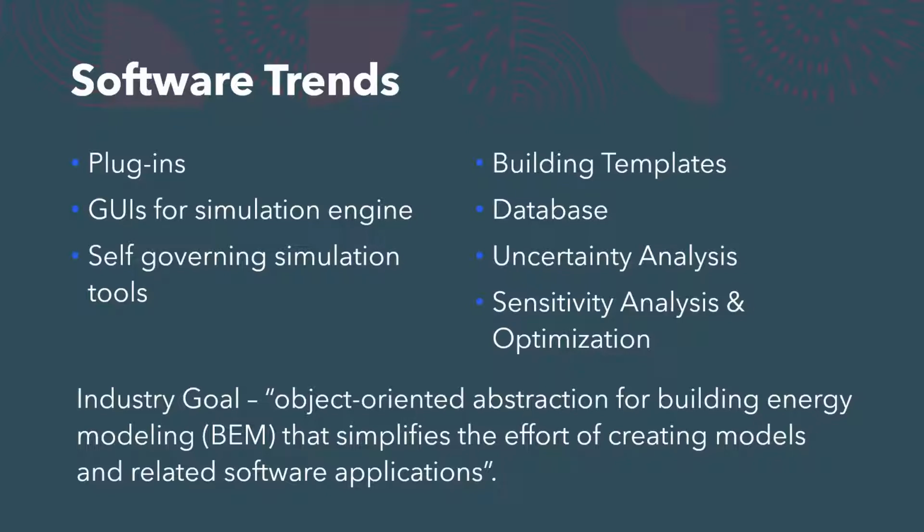That means instituting self-checks and balances within the program itself to help users. We like building templates, i.e. workflows and best practices, to get us started or let us know where we should be heading in the general direction. We like to build up our databases, and probably the two things that we use our programs for are uncertainty analysis, and sensitivity analysis and optimization. The uncertainty analysis is posing what-if questions. What if we change the window to wall ratio? What if we rotated the building 180 degrees? What impact is that going to have on the project?